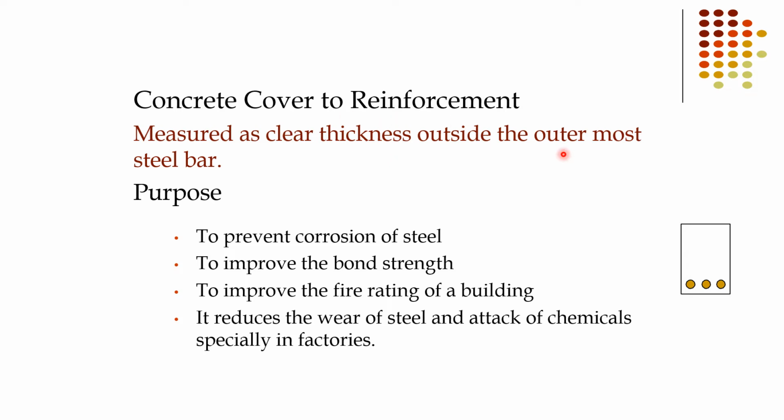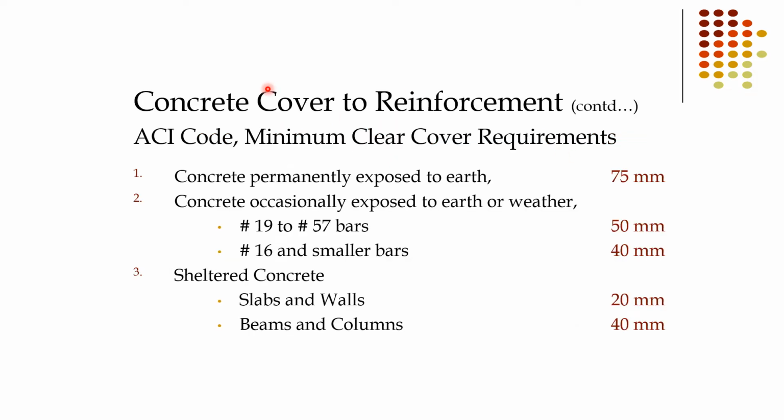Concrete cover to reinforcement. Here are the minimum clear cover requirements as per ACI code. Concrete permanently exposed to earth, for example foundations, you have to provide 75 millimeter cover. Concrete occasionally exposed to earth or weather, where rainy, etc.: for number 19 to number 57 bars, 50 millimeter. For number 16 and smaller bars, 40 millimeter.